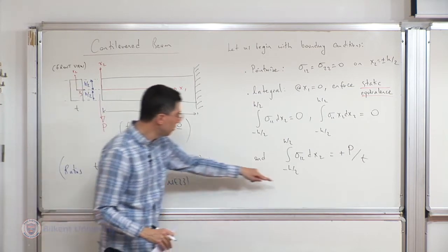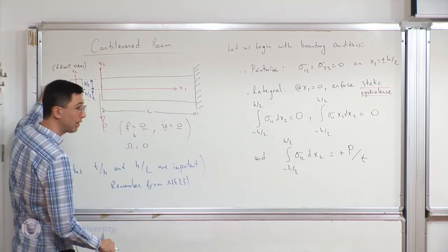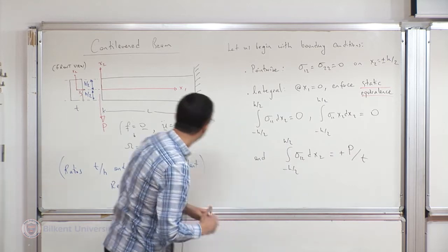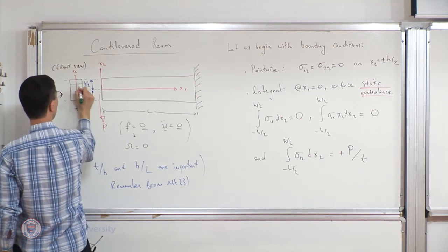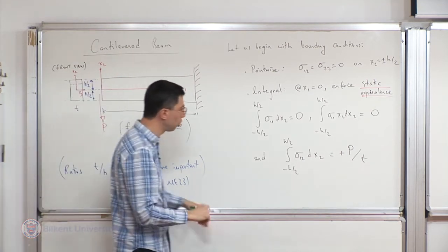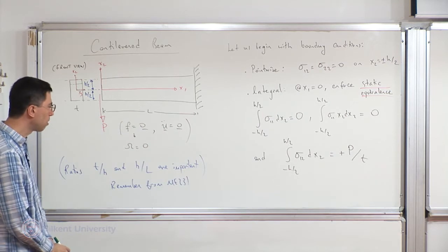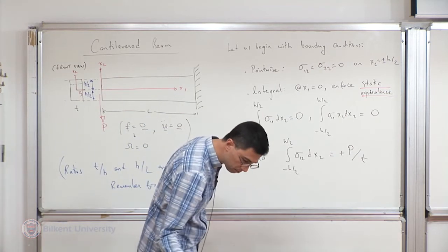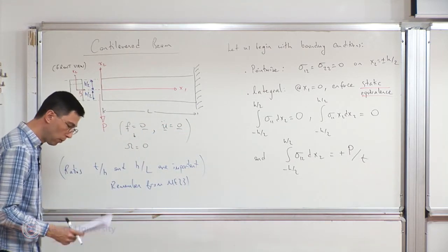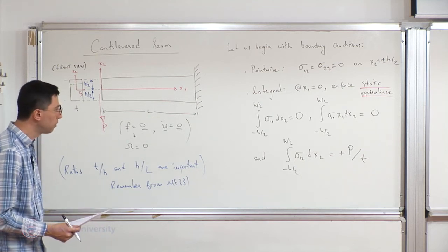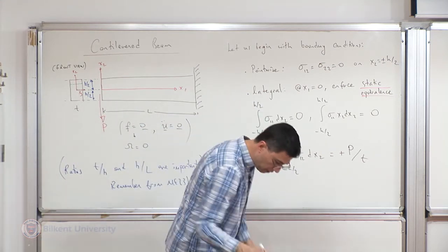So in other words, this integral really represents the average shear stress along a line that I take. If it's plane strain, it's not a problem. But if it's plane stress and t is not that small, there might be variations in sigma 1,2 along the green line. But if I average it, I should be pretty close to the pointwise value of sigma 1,2. So sigma 1,2 is really the average stress along that green line. In an ideal plane stress setting, it is what we are computing. It is supposed to be exact within the limits of our approximation. So those are the boundary conditions on stress.